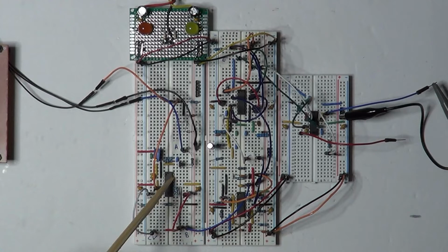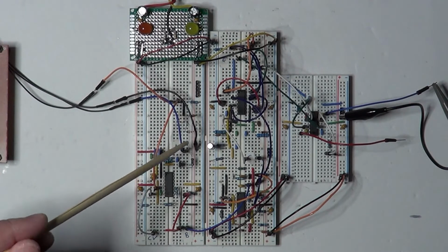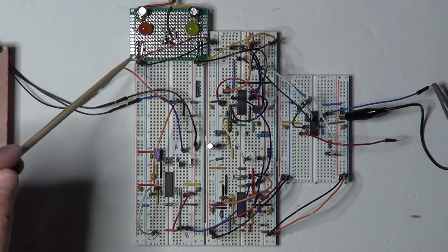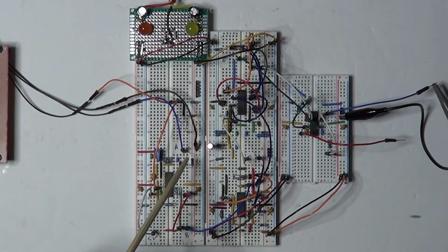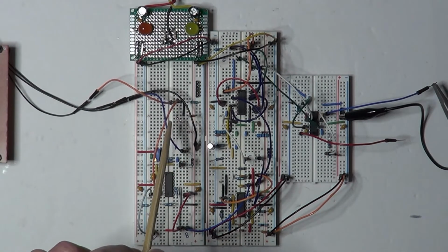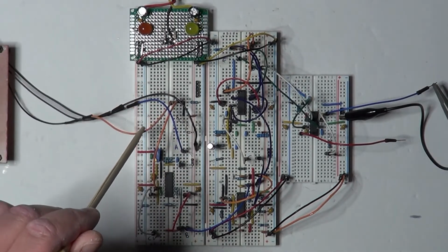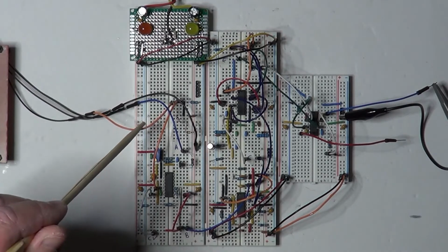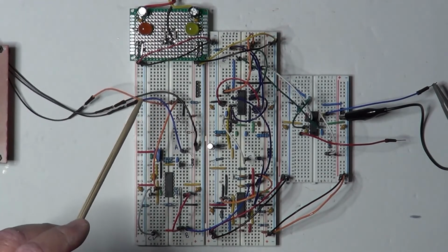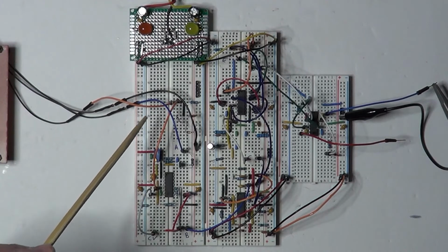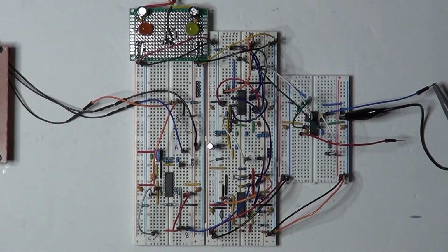One actually controls the transistor itself, and the other 2 generate the buffering for impedance adaptation of the control voltage generated by the keyboard itself. These cables are those that go toward the keyboard, 1, 2 and 3. One is the one with the current generator, this blue one. This is the ground, and this is the return, basically the point F in the schematic, where we get the control voltage generated by the keyboard and we use it internally in the rest of the circuit.